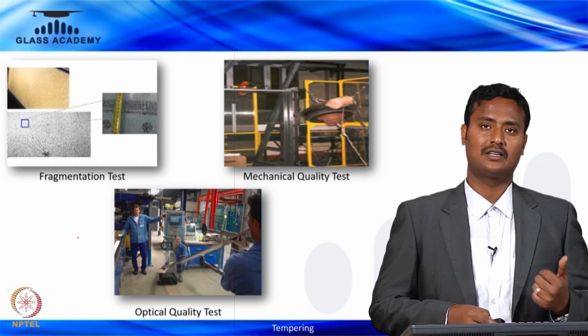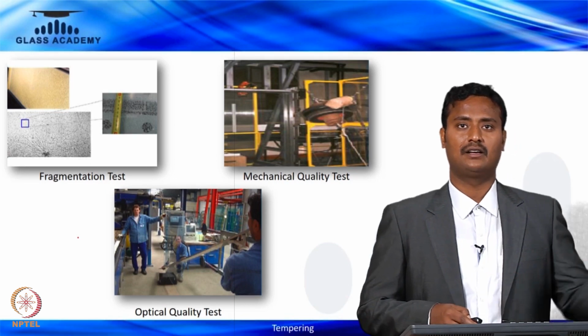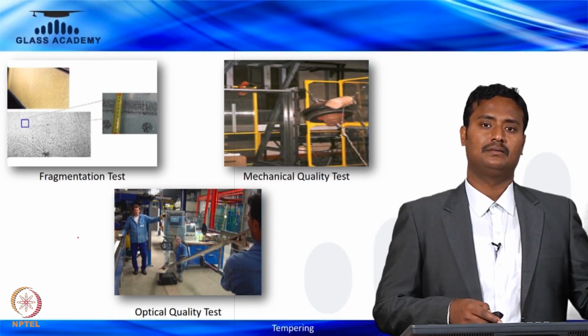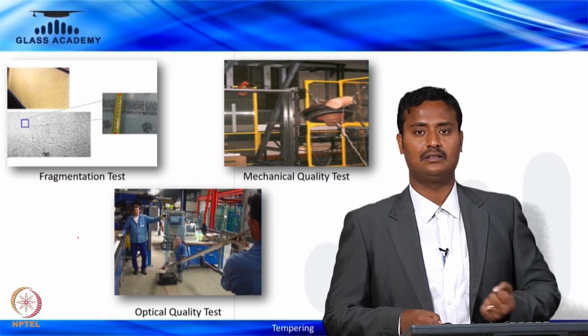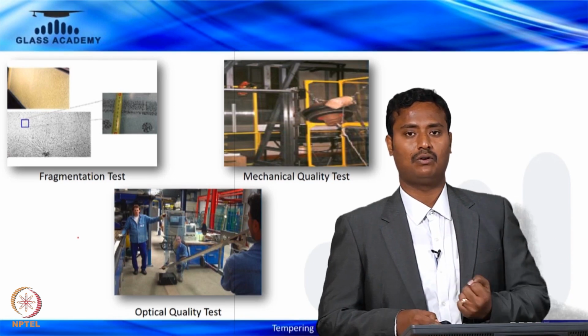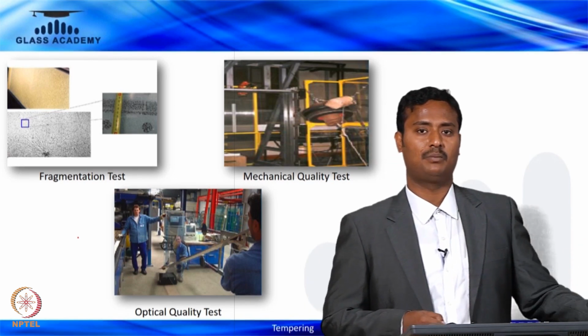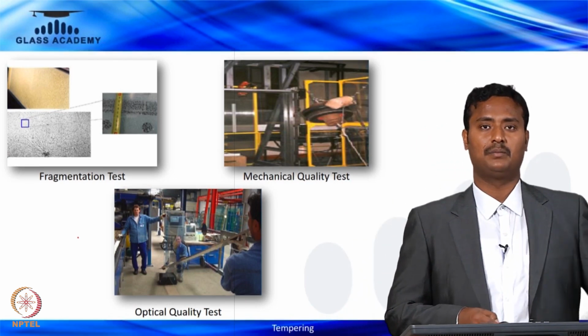And the mechanical test, like the soft bag test: a 5 kg soft bag is lifted, like a pendulum test, and dropped from a height of 250 centimeters. If the glass does not break, it passes.